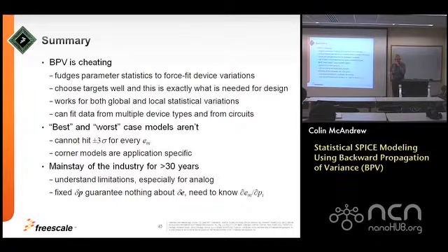That's a good question, and the answer is that we actually do. There are some quantities, sometimes parasitic series resistance, and the best example is the non-ideal component of base current, which has a monstrously wide distribution, and physically it should have. What happens there is that they're better modelled by a log normal than a normal distribution, and what we do then is we put an exponential mapping in the model file. So rather than having p plus the variation or being multiplied by 1 plus the variation, we exponentiate that, which then converts the normal distribution for the parameters into a log normal distribution for the variables.